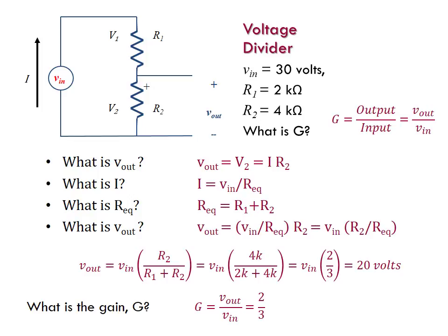If we really want to run through the math on this, which I encourage you to go through, it's not hard. Voltage dividers are pretty simple. V out equals V in times R2 over R1 plus R2. We can simplify this into a function of gain, where gain equals V out divided by V in by definition. Usually we're taking some percentage of the total V in voltage and giving some percentage of that voltage to the V out. What that percentage is depends entirely on the ratio of resistors that we've chosen.